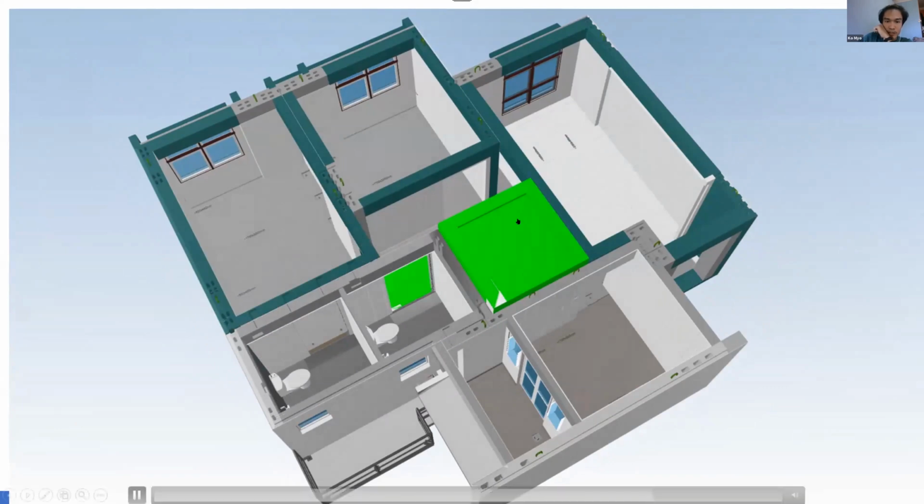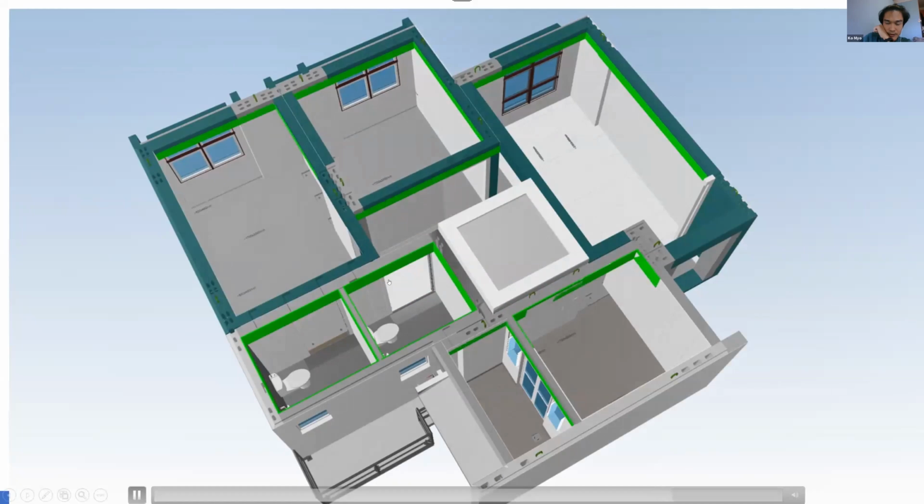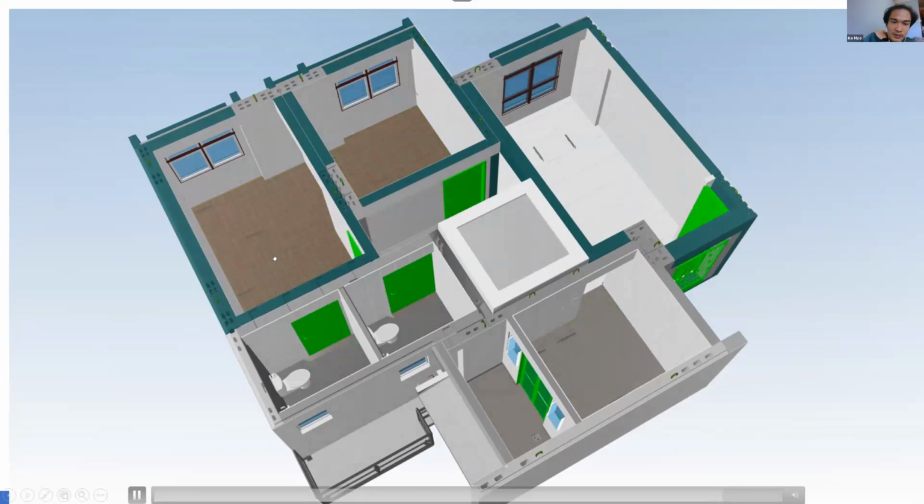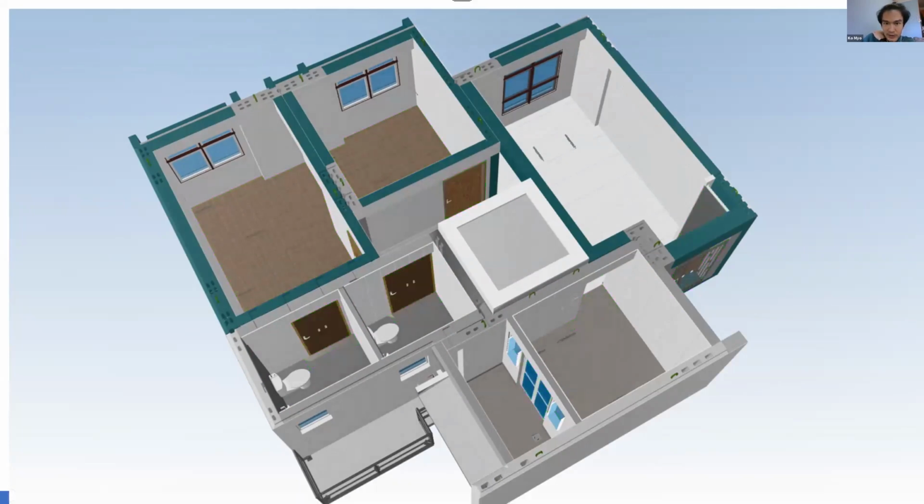So the last one will be the house center, and then the cast corridor at the latest part. And PVC tile, I mean, floor finishes will be coming later. And door frames and door panels are the last to be installed. And skirting is the last to be installed. So basically, this one shows how the unit is going to form.